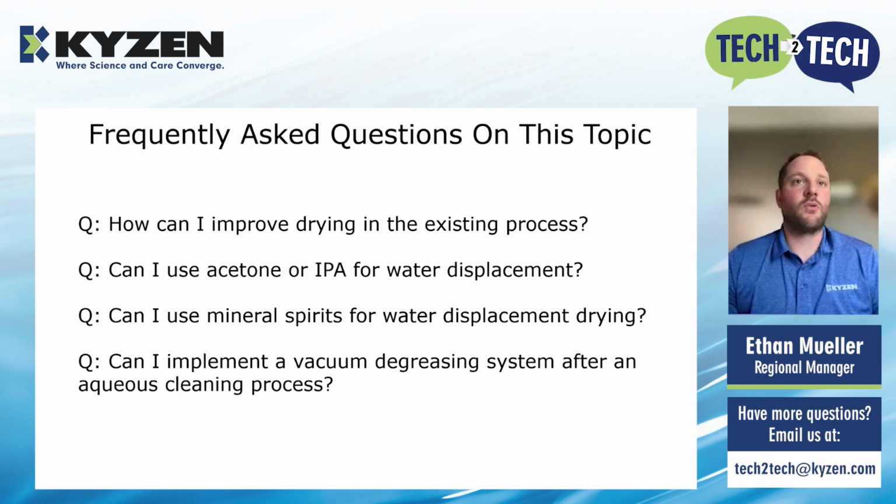Can I use acetone or IPA for water displacement? Yes, you can absolutely do this. These are commonly used commodity-based products. I would just be careful with these. They are flammable, they are very volatile, and they stink. So you can use them, but there are other, better options on the market that may even prove more cost-effective than these commodity-based materials.